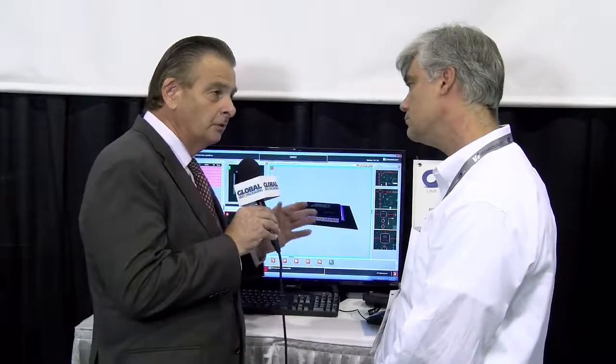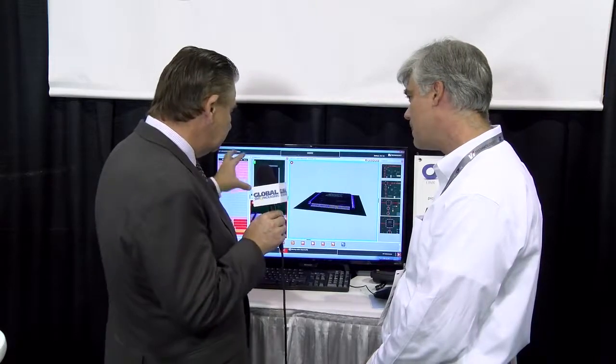Are there any elements of self-learning in this AI? I'm not sure what you mean. Well, the system picks up defects at SPI and flags them again at AOI. Does the system learn as it goes along, or is it simply: yes, it flagged a warning here at SPI, therefore it's definitely going to flag, and that's it? Right. Each system is designed to methodically give you the right answer every time. It's based on explicit tolerances that are set for every failure category. So there is no learning from that standpoint.